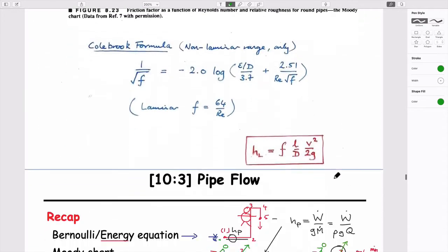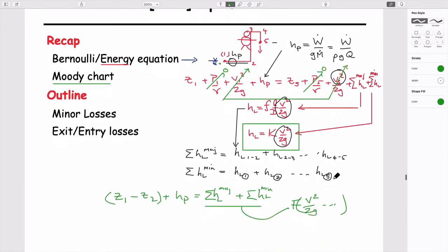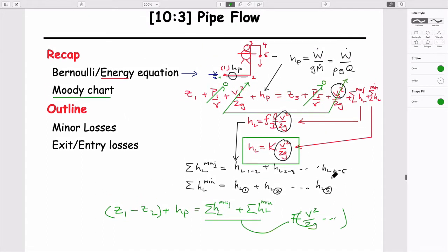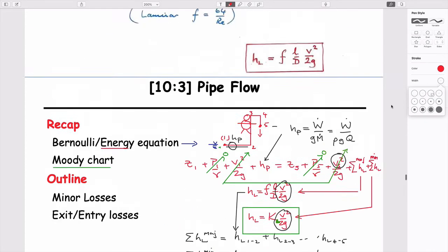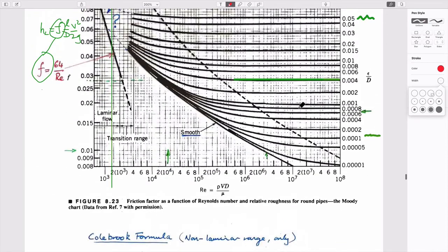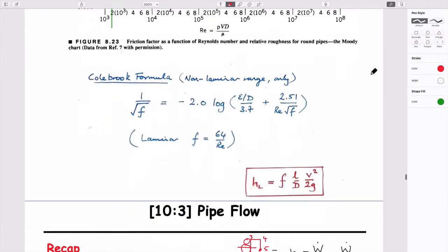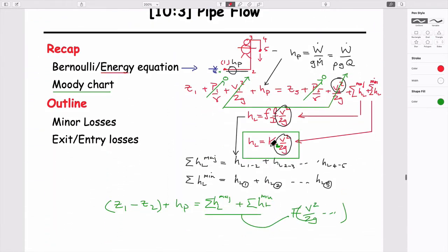So the fact that we tend to represent the minor losses by a coefficient, K sub L usually, is merely suggesting the fact that always in pipes the flow is assumed to be turbulent, because it's equivalent to being in this region on the right side here, where it doesn't change with Reynolds number at all. It varies only with the physical characteristics of the pipe. Those happen to be the roughness of a pipe, or for individual fittings, it would be the geometry of the